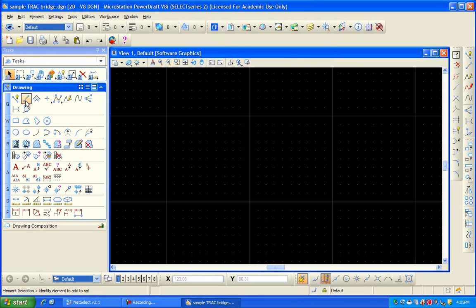It says place line, so I do a data click there, and you'll notice anytime you punch a toolbox or a tool button, it'll show that that box is selected, and a lot of times it'll pull up an auxiliary command toolbox, which gives additional information you can use for that tool. In this instance, I want to specify that my line is 10 inches long, and for right now we'll even say that I want it to be 0 degrees.